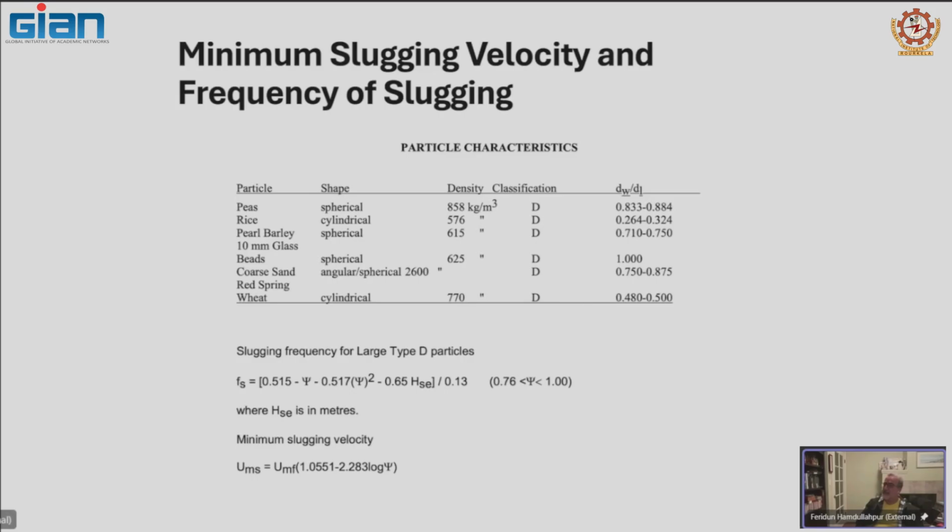As I said, in certain drying applications, you may want to use a spouted bed because you need to keep the grain longer in the bed, but not necessarily subject to the airflow. So you provide airflow in a way that is only enough for the core, but not needed in the surrounding region, so that the particles could stay there longer and have the moisture removed through diffusion. Once they reach that stage, it doesn't matter how much they are exposed to the air.